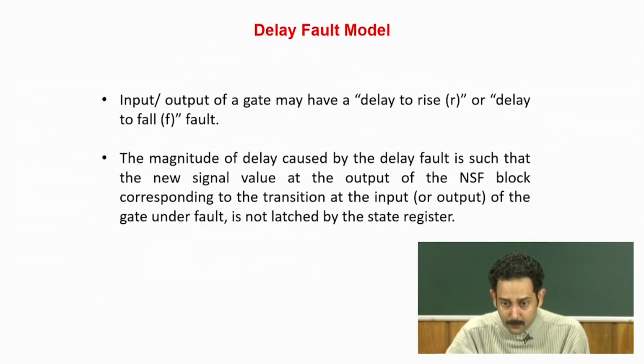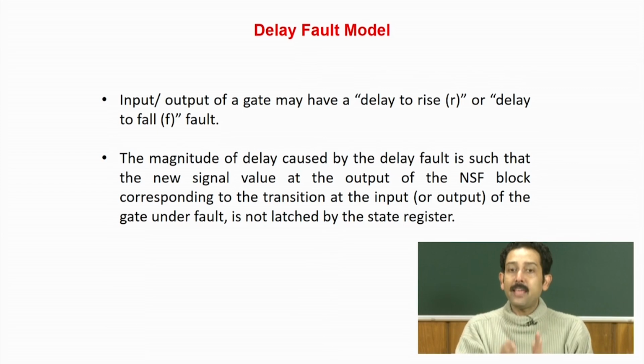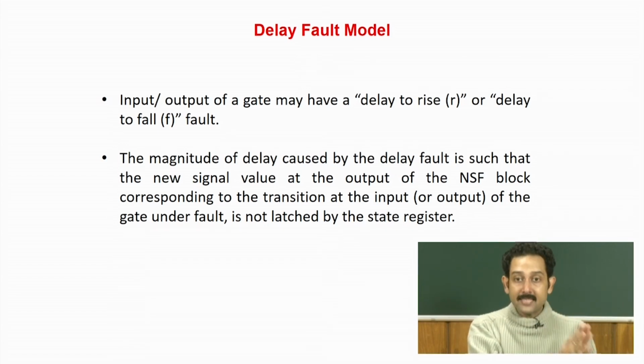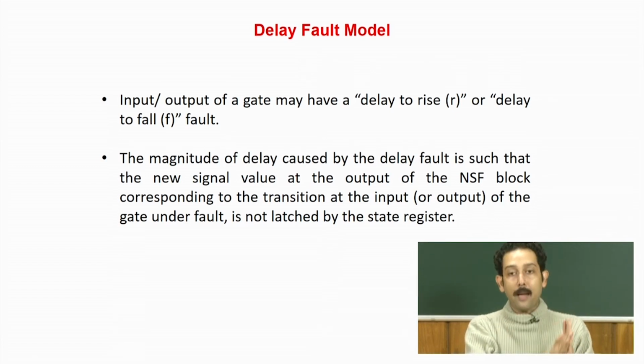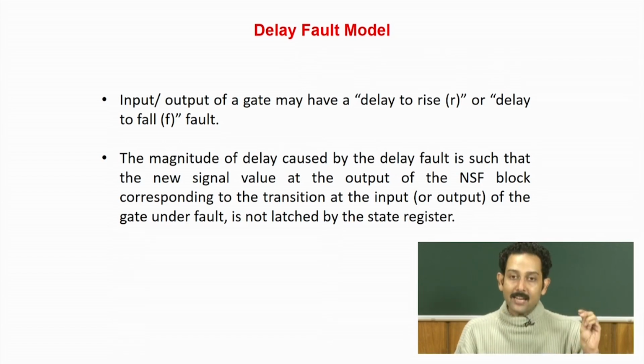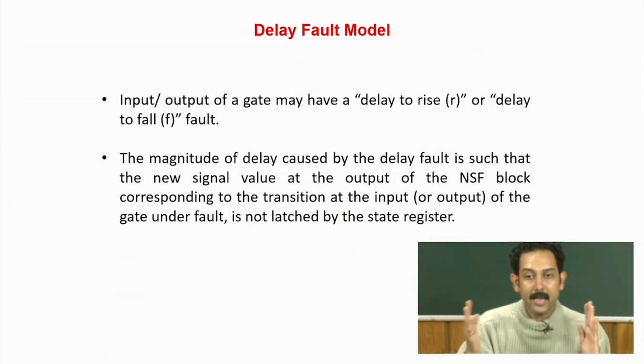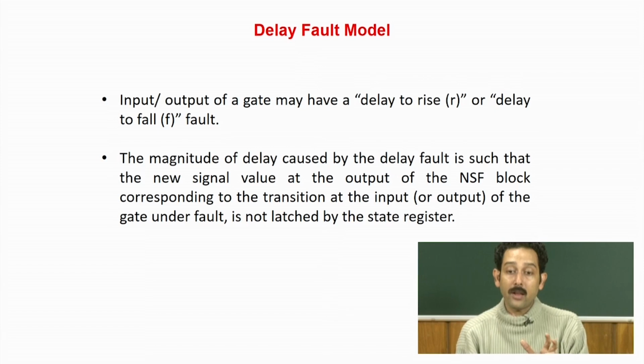So another very important fault model is the delay fault model. So what is a delay fault model? Nowadays circuits are operating at the gigahertz level. So you should know not only that the circuit is operating properly, that it does not have any coupling fault or any stuck-at fault, but also that the answer comes in a predefined amount of time. The AND gate should compute the value 0 0 to 0 or 1 1 to 1 and so forth for all the gates in a predefined amount of time. That is, the delay from one end of the circuit to the other should be such that it can meet the speed requirements. So the delay fault model is a very important fault model for most modern circuits, and almost all circuits nowadays also cover the delay fault test.